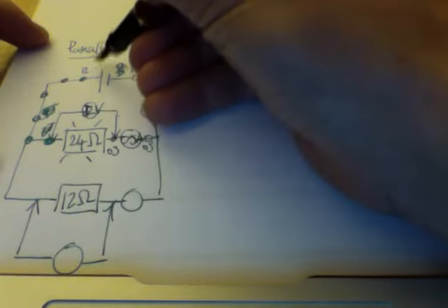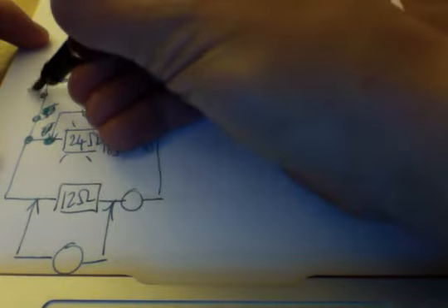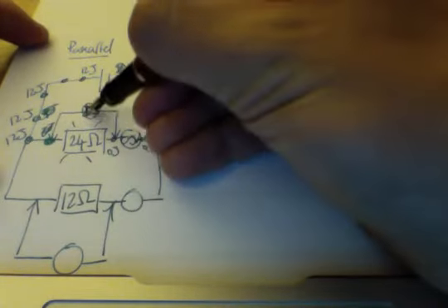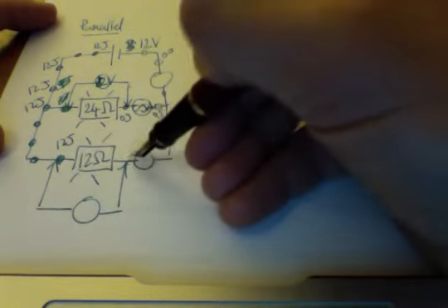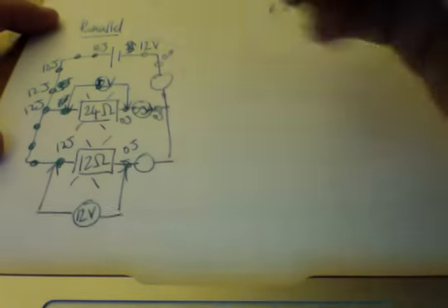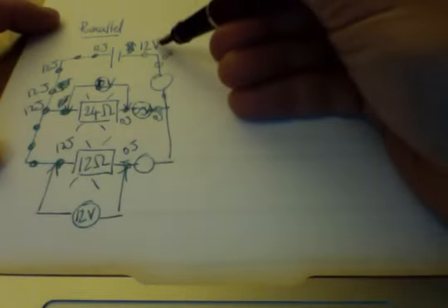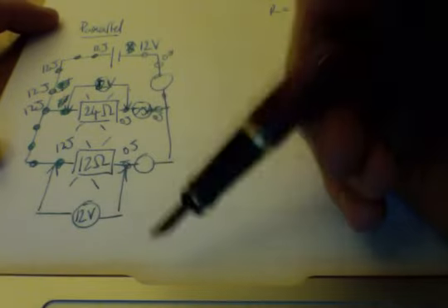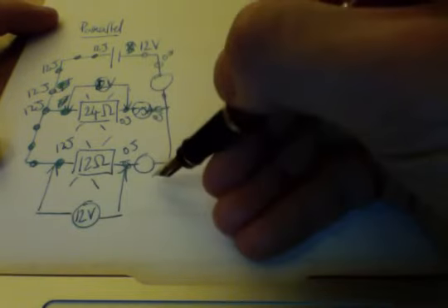This is coming around with 12 joules on each because we have a 12 volt battery this time. Okay, so it's coming around with 12 volts. If it makes the choice and goes the long way around, it comes around, it's got its 12 joules and it's giving up all of its energy to that battery and leaves with no joules. So therefore we have 12 volts. Remember, in a parallel circuit, the voltage stays the same whichever branch you're dealing with.